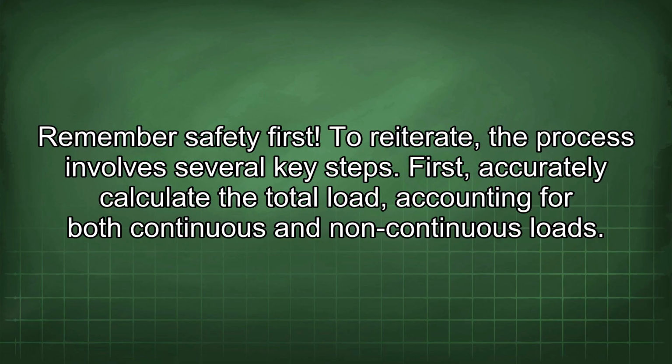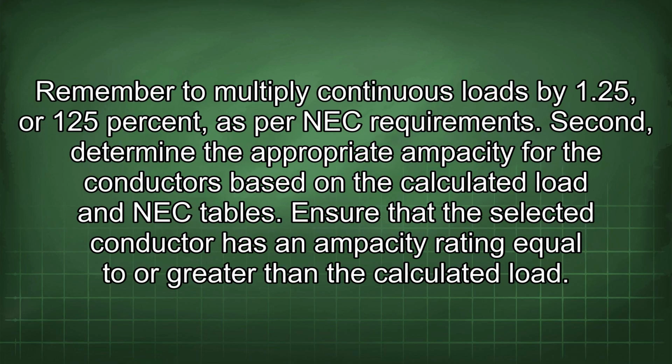First, accurately calculate the total load, accounting for both continuous and non-continuous loads. Remember to multiply continuous loads by 1.25 or 125% as per NEC requirements. Second, determine the appropriate ampacity for the conductors based on the calculated load and NEC tables.